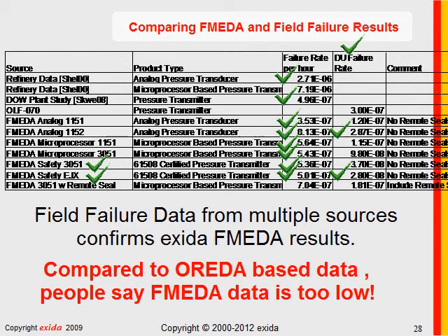That's the direct result of new technology and why it's so important to predict the dangerous undetected failure rate as compared to the total failure rate. But never compare total failure rate to the dangerous undetected in an FMEDA. That makes no sense.